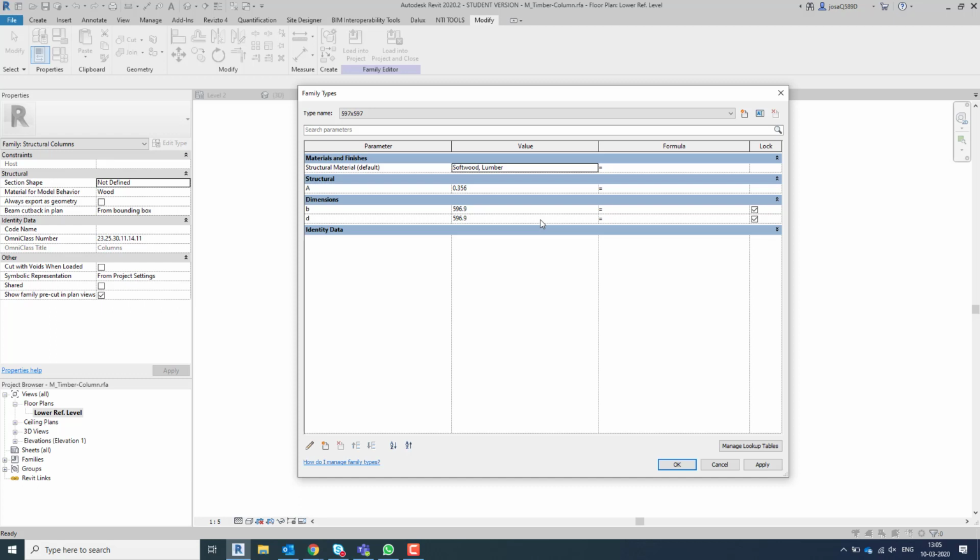In other words, we have to know the volume of every single component. So we have to know the volume of a column, the volume of a path, the volume of a wall. That means the three dimensions: base times depth times height. And then once we know the volume, we have to multiply this volume times the specific CO2 embodied according to that material. We find these data from inventories, official inventories, or manufactured products. So we need to know the volume of every single element and multiply that times the specific CO2. In this case, we have two values.